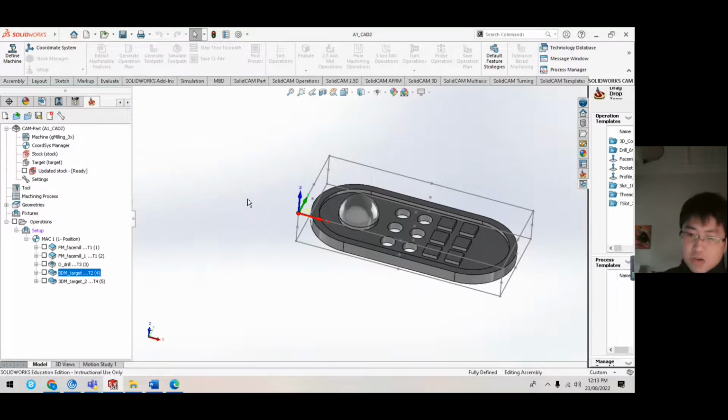After we have these 6 holes, we can remove the 2 rectangular blocks which held the stock object in the beginning 2 steps. Because we have these 6 holes, we can use the slot at the bottom as the holder, with the T bolt and nut to fix the stock through these holes. Then the stock can be held stably for the later procedures.